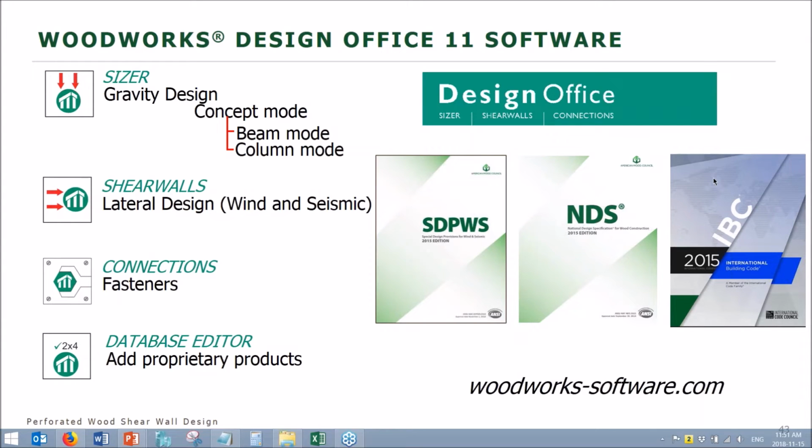The shear wall software, which we're going to talk about today, is responsible for the lateral design. So it can generate automatically wind and seismic loads. It will then distribute those loads through the structure using either the rigid diaphragm assumption or flexible diaphragm assumption, and then it will design those individual wall segments based on either the segmented approach or the perforated approach.